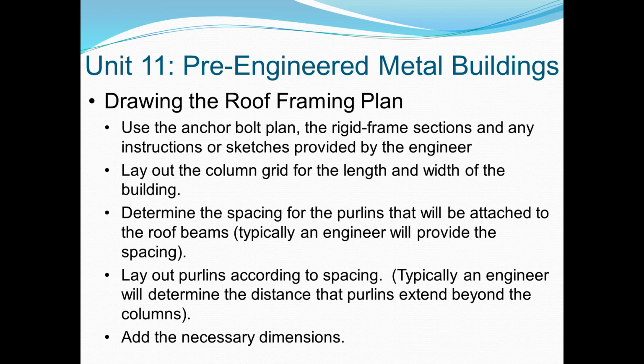We will determine the spacing for the purlins that will be attached to the roof beams. Typically, an engineer will provide the spacing. Lay out the purlins according to spacing. Typically, an engineer will determine the distance that purlins extend beyond the columns, and then add the necessary dimensions.